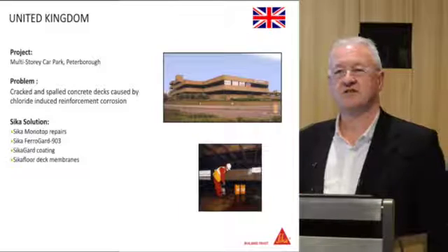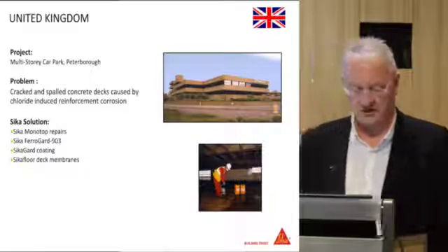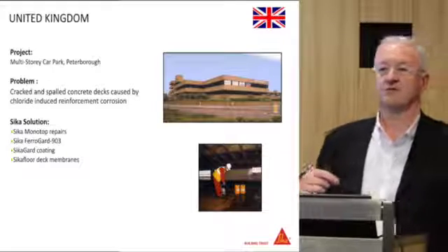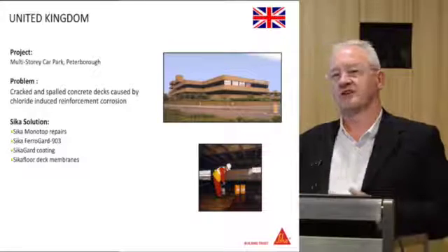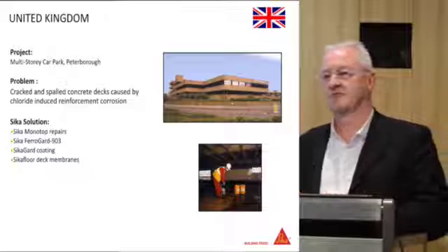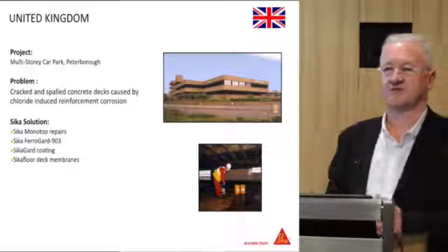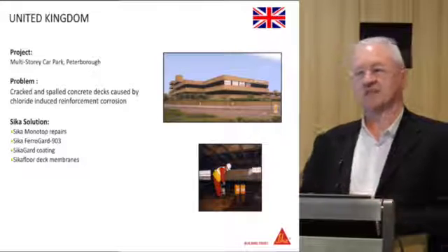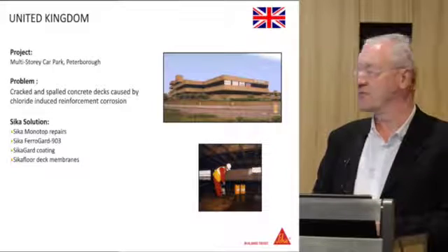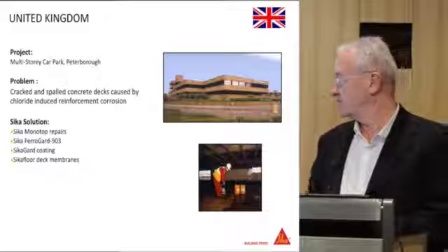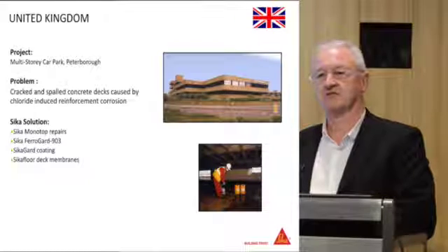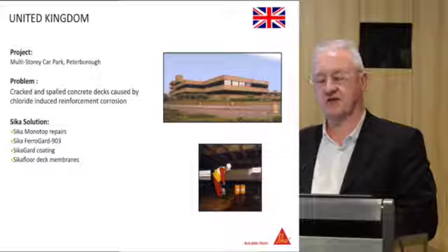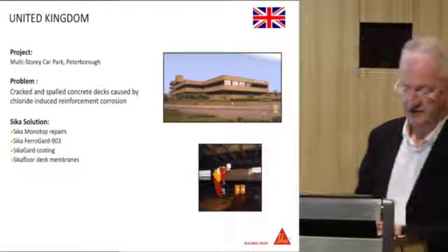Car park, I've mentioned earlier how we treat car parks. In this situation, the chloride levels on the decks weren't particularly high, so we managed to use the inhibitors on the decks. But of course, if they were really into the range of 1, 2, 3%, and issues with low millivolts from half cells, then obviously it would be a completely different game altogether. We'd probably have to look at CP or galvanic protection.